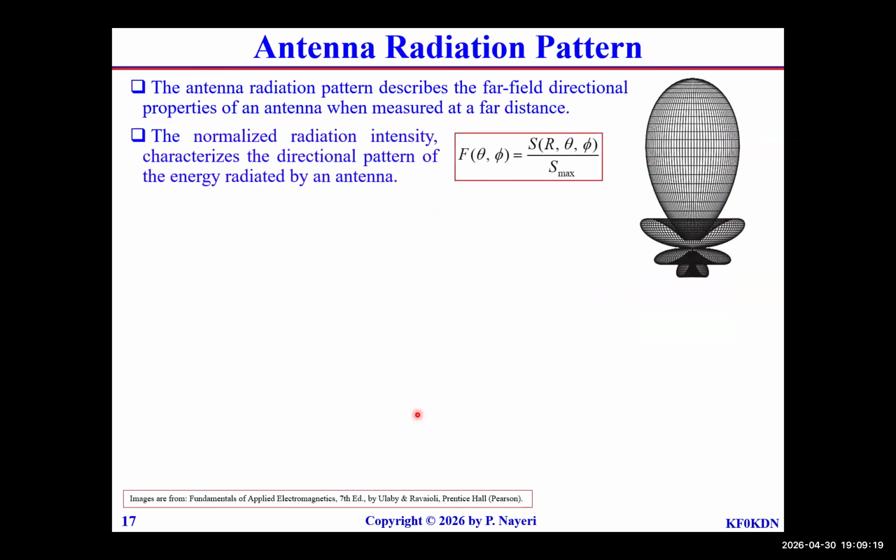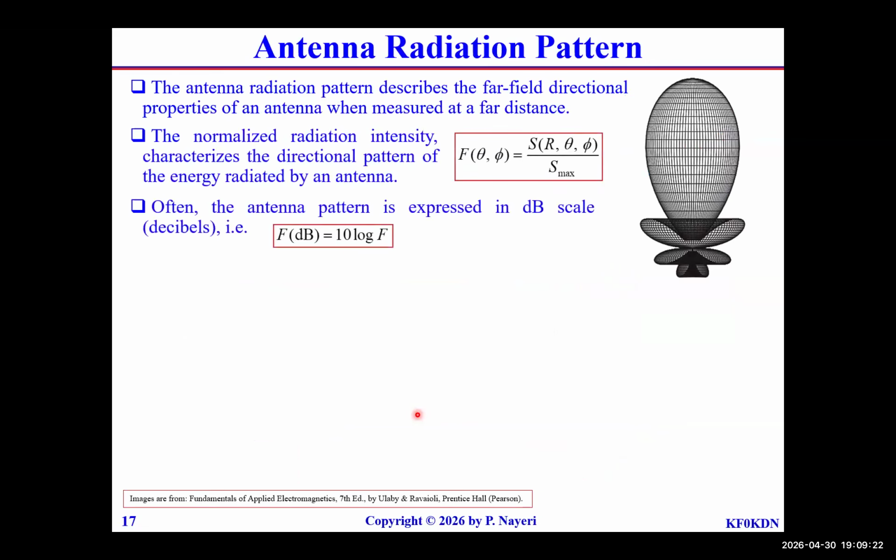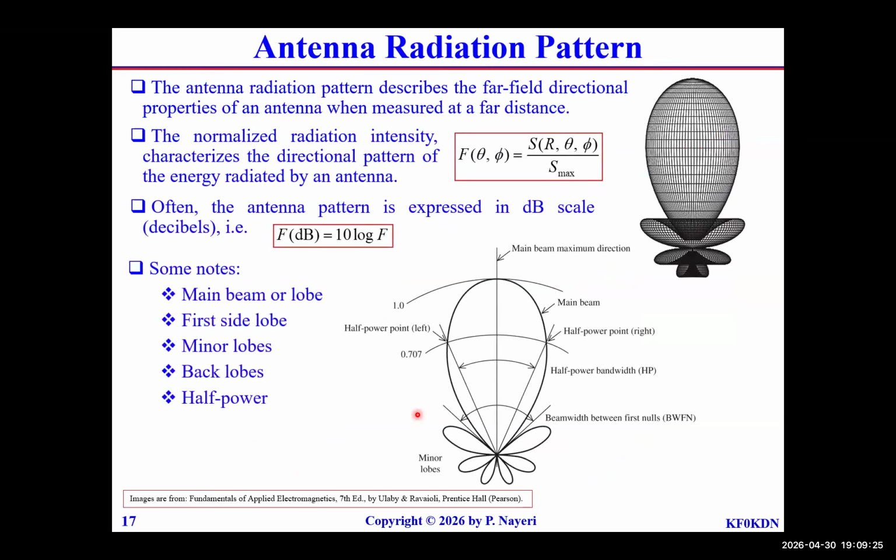So as mentioned, any type of antenna has a certain directivity associated with it. An antenna points the power into a certain direction. So effectively, it's a spatial type of filtering. In the case of an antenna, typically you have a main beam pointing in a certain direction, assuming it's a symmetric type of radiation pattern, which mostly are. You see I've marked these 2 points as the half power point on the right, half power point on the left. This is going to be where the power drops to 1/2 or minus 3 dB down from the peak that you have.